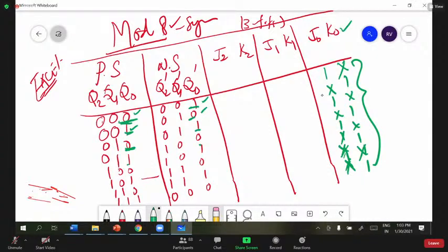Can't you write the expression using a K-map? You can make use of these don't cares and ones, put them in a 3 variable K-map, and find the expression for this. You can find it in this way. Suppose this is there, how do you find this? For K0, you can take a 3 variable K-map like this. You can put it here.